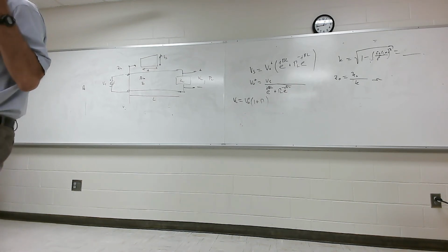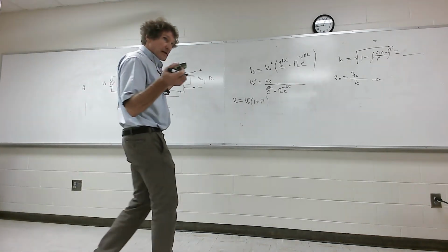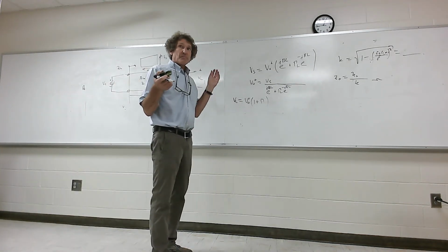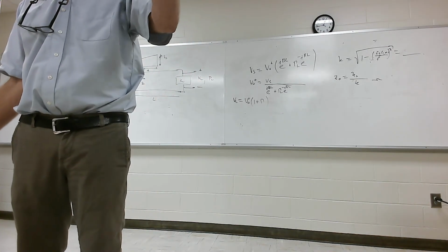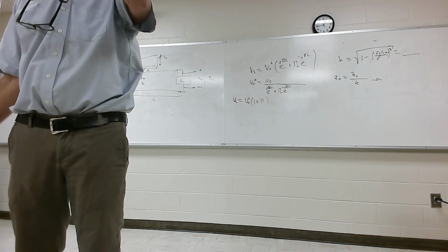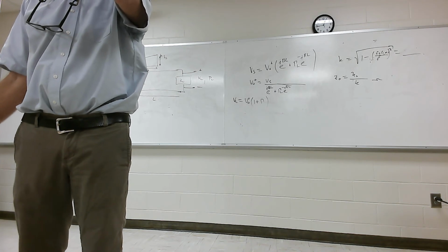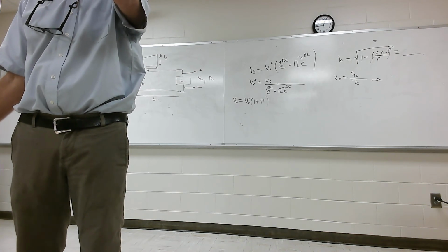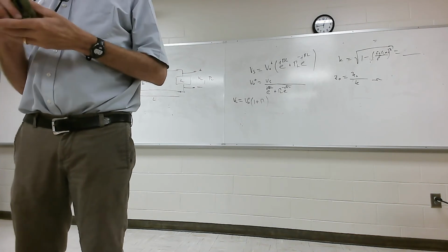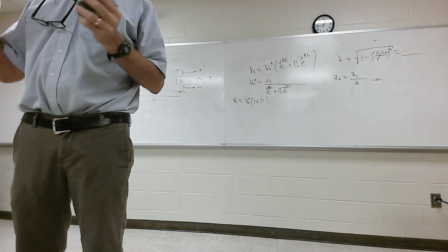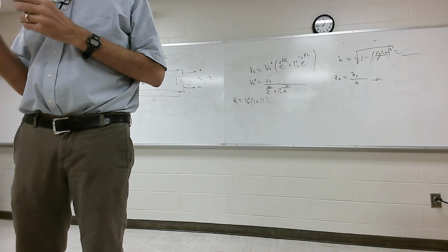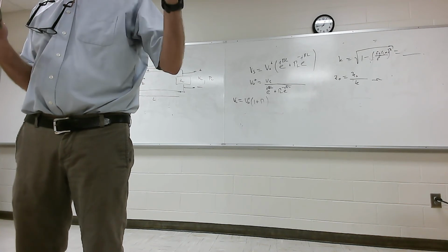If it's not, you can calculate the current, right? And you can calculate the current by taking V load divided by Z load, and then saying it's 1/2 the current squared times the real part of load impedance. Do y'all follow me on that? Or you can take 1/2 the real part of voltage times I conjugate. But remember, it's only the real part of the impedance that dissipates power.